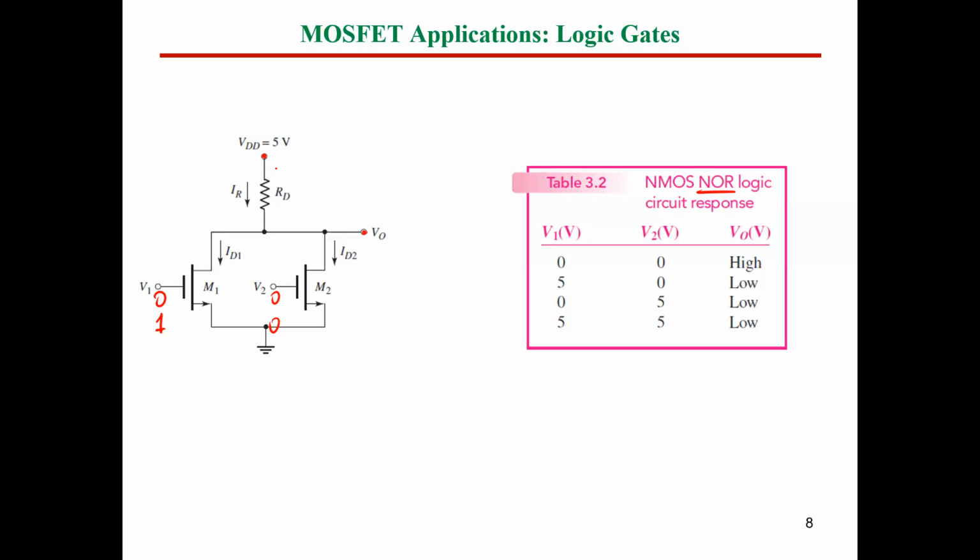So we can consider that the voltage here is almost very small, and the signal at V out now would be active low, okay? Because most of the VDD voltage will be consumed as voltage drop on RD. And in this case, the output would be active low. So once we apply an active high signal, which is equal to VDD, here in V1, we are sure that the output would be active low.